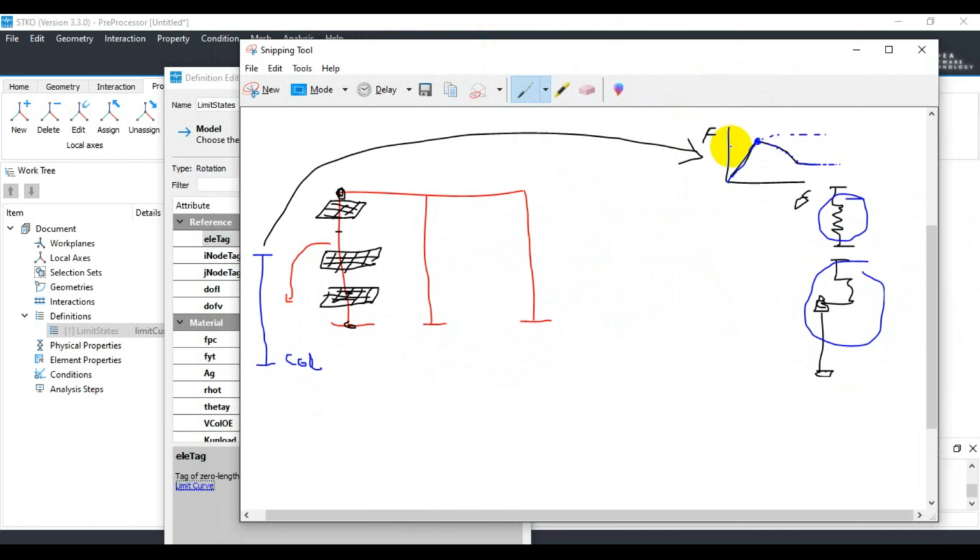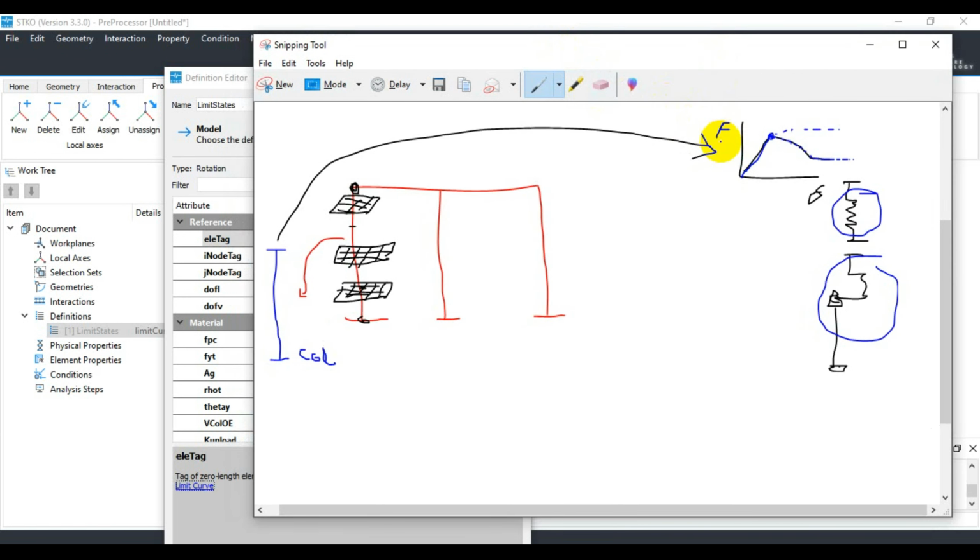Based on those limit states, we can relate the shear demand to the drift at shear failure based on the transverse reinforcement and axial load ratio. We can also find the intersection of the idealized load deformation curve and the limit state surfaces defined by the capacity of the model, and we can study those in our OpenSees models.